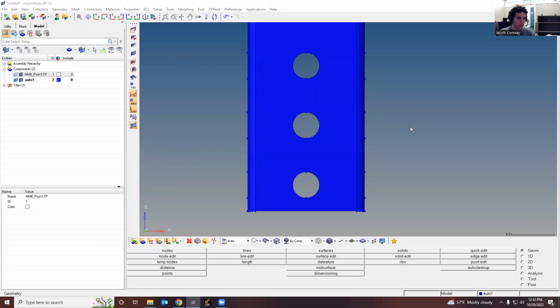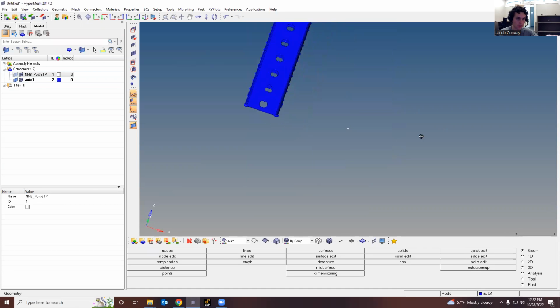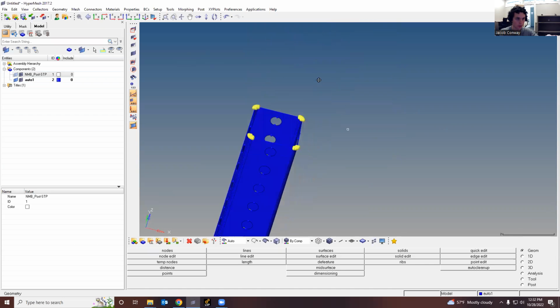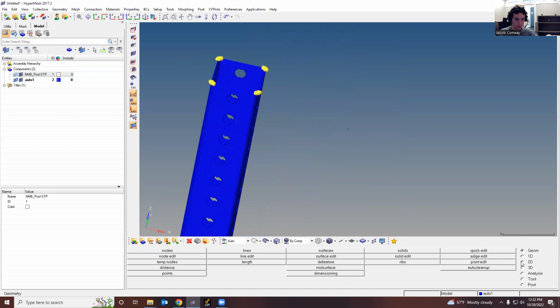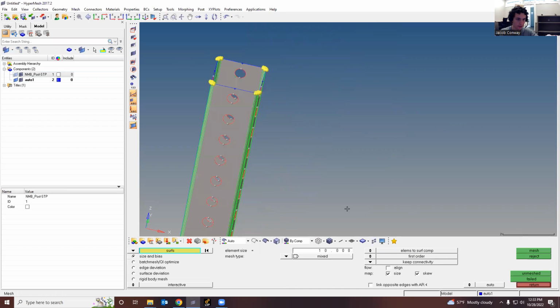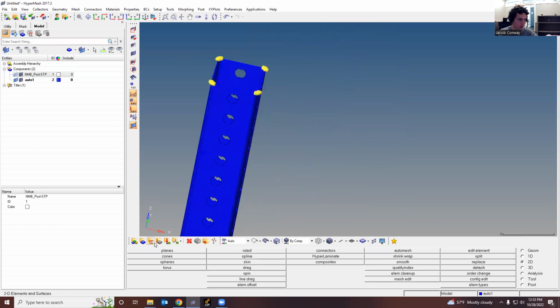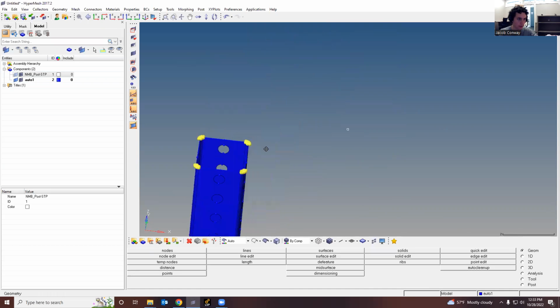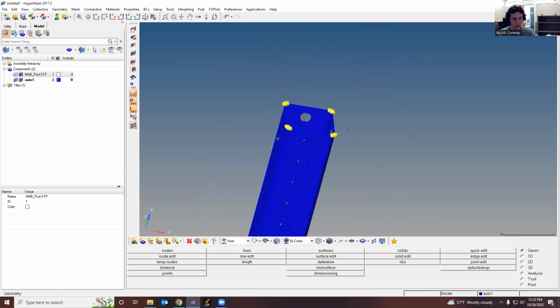All right, now we actually have our surface to mesh. To do this, we are going to use the tool Auto Mesh, and we're going to want to choose a reasonable size. I did some measuring beforehand, but I'll show you some measuring. Generally, you don't want to have too large of a mesh, otherwise you can't get all the details of the shape that you want.